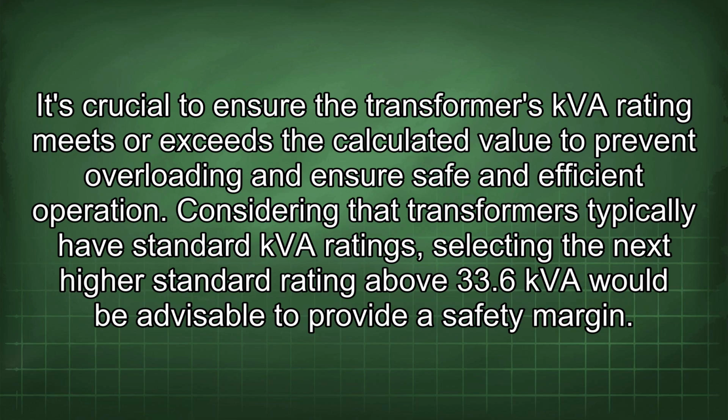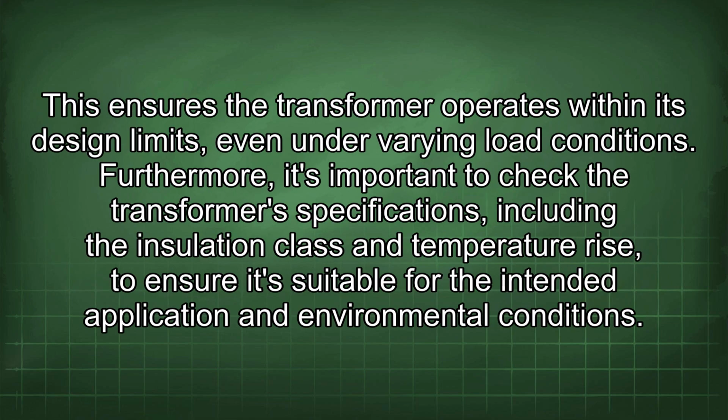Considering that transformers typically have standard kVA ratings, selecting the next higher standard rating above 33.6 kVA would be advisable to provide a safety margin. This ensures the transformer operates within its design limits, even under varying load conditions. Furthermore, it's important to check the transformer's specifications, including the insulation class and temperature rise, to ensure it's suitable for the intended application and environmental conditions.